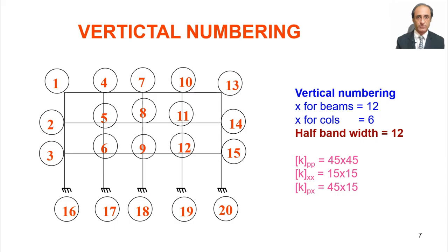because not just the memory, sometimes when we run, if our structure is too big, we get the message that we cannot have more, the number of joints is more than permitted. So basically the problem is that the size is so large that the program says that it's beyond its reach. So numbering has to be done such that we get lower bandwidth.